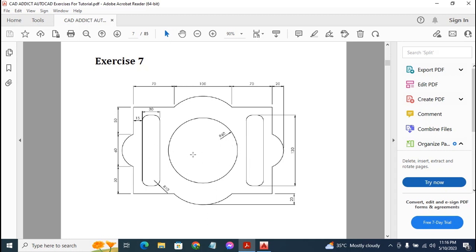So we are going to offset the vertical construction line at a distance of 120. If the entire length is 240, that means the center will be at 120. Then we'll offset the horizontal. Sorry, we are going to locate the midpoint of the width of this rectangle, which should be at, if the entire length is 160, then the width should be at 80 millimeters.